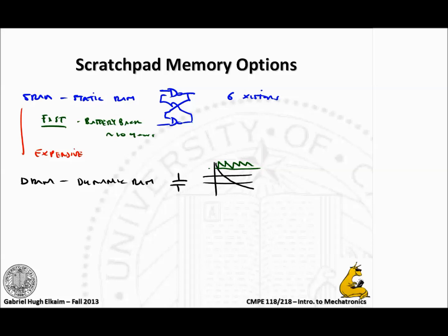So the good advantages are it is cheap. All right, very cheap. It's dense, meaning you can get huge amounts of memory in small packages. On the disadvantage, it's slow, and it's ESD sensitive, which means you have to take certain precautions when installing it. If you just mishandle it and you've got some static electricity on you, you will actually blow the little capacitors apart, right? And then they won't work.